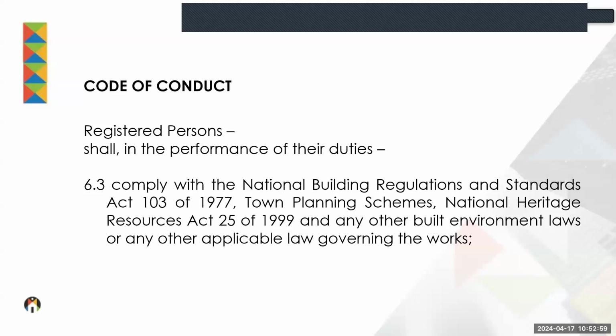They must ensure that, for instance, the National Heritage Resources Act is applied, and that there are other requirements about sensitive areas where there might be prohibition in terms of national acts to do developments. That is their duty. But when they look at our building plans for approval or refusal, what we as professionals have to do is only provide them with the minimum requirements in the National Building Regulations.